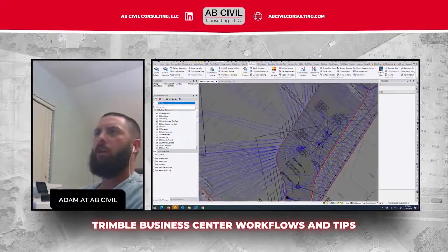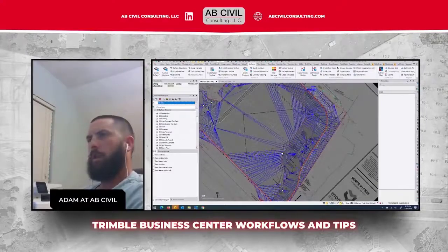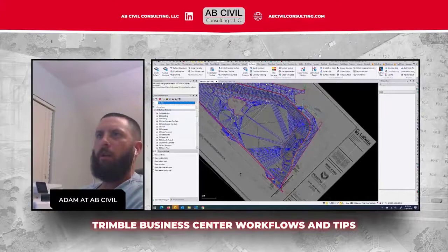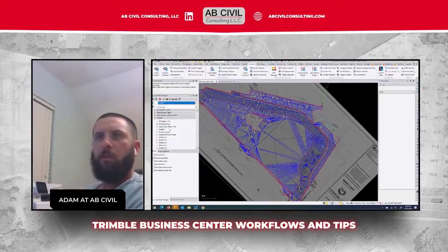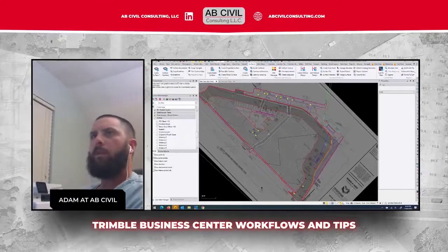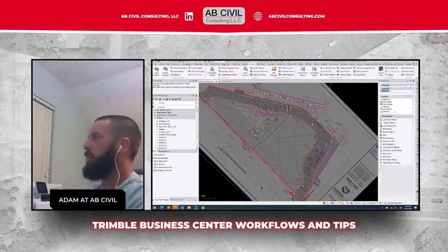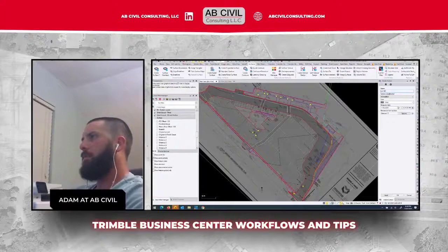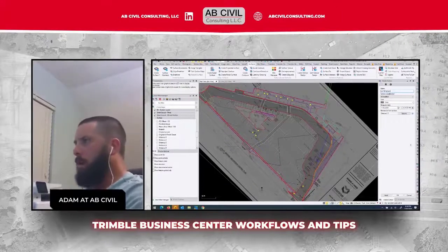Well, actually, one thing I should show is a quick cut fill map of those. Actually, I'll show how to get all those surfaces onto one, all the undercut surfaces into one surface, and then make a quick cut fill map. So what I'm going to do is I'm going to go to Surface, Create Surface. I'm just going to say Cut Fill Surface.